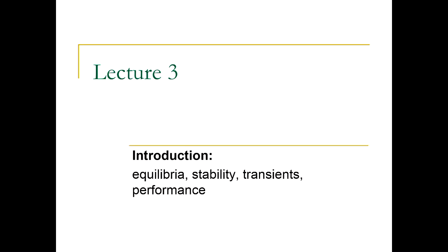So whenever you're dealing with a problem, you would need to model it. Typically, models are nonlinear. You would need to find equilibria, then maybe linearize around that equilibrium. We will talk about linearization later. And then you will need to design your controller so that its closed loop satisfies stability. We usually design stable systems.